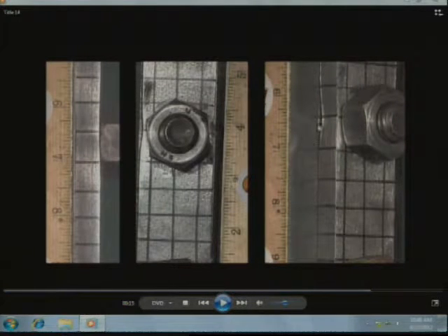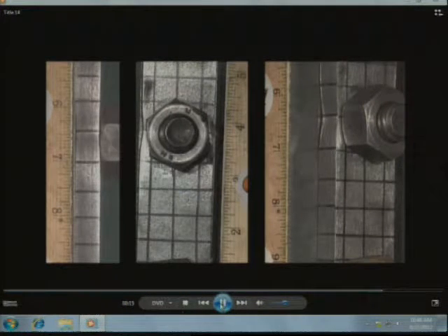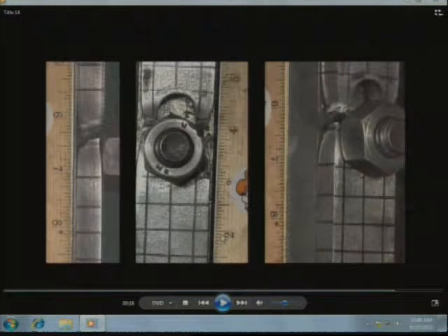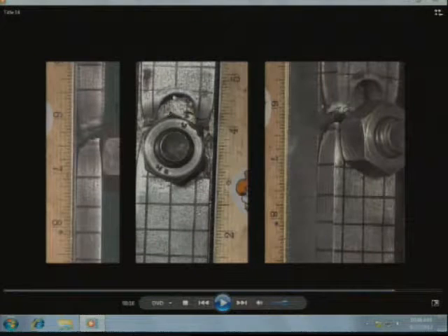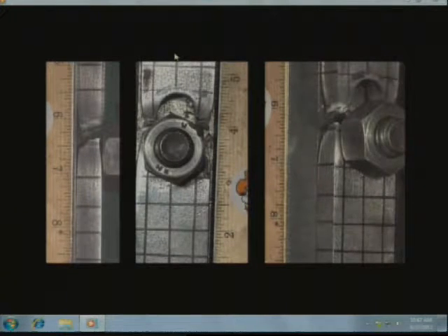If it's actively being loaded, I would run. And then as we keep going, it necks further, right? See it necking further down. But again, we don't see a lot of movement here. And it broke. Now we were using hydraulics to load this. The cool thing about hydraulics is that when it breaks, it just lets go. It's not pushing. If this was gravity loads, what would happen? This would shoot off, right? It would fly. And that is failure. That's what we'd like to avoid, at least failure of a fracture connection. You with me? That's what we'd like to avoid.